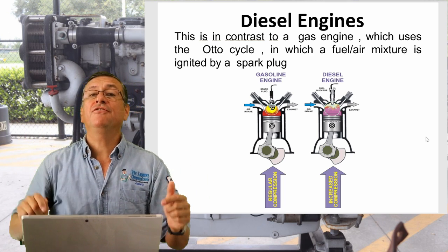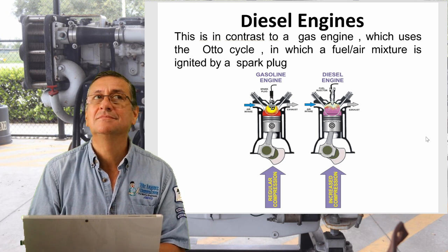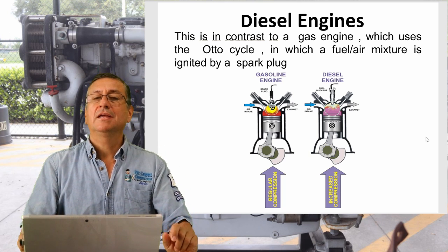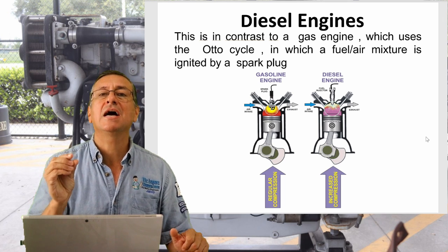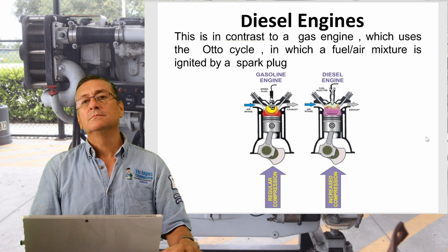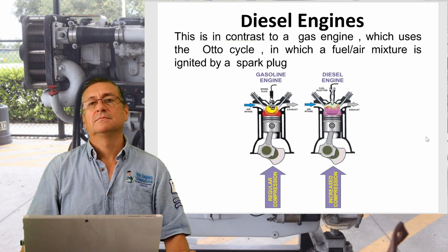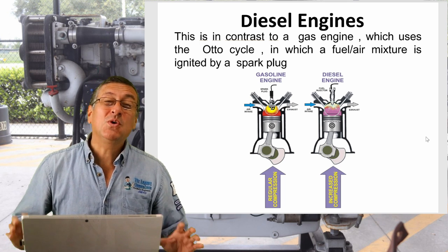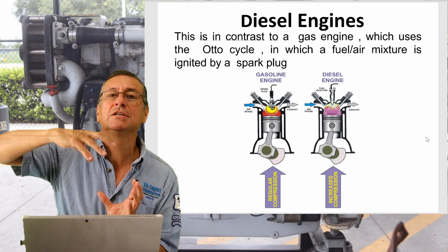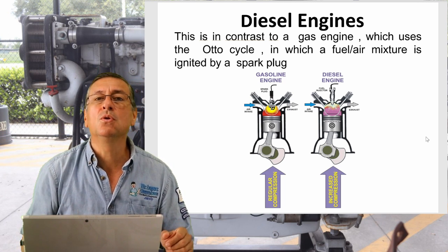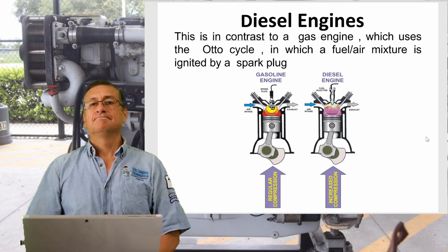What engine is more efficient? The engine that burns more air with less fuel. The diesel engines are the more efficient, because in a diesel engine you can introduce the maximum amount of air with the turbos or superchargers, and with a small amount of fuel, burn more air and produce more torque. That's the reason.